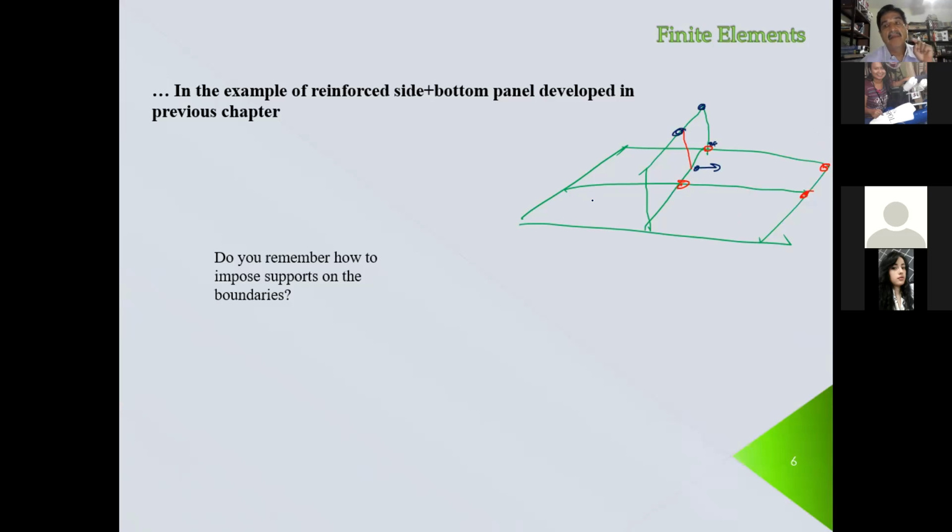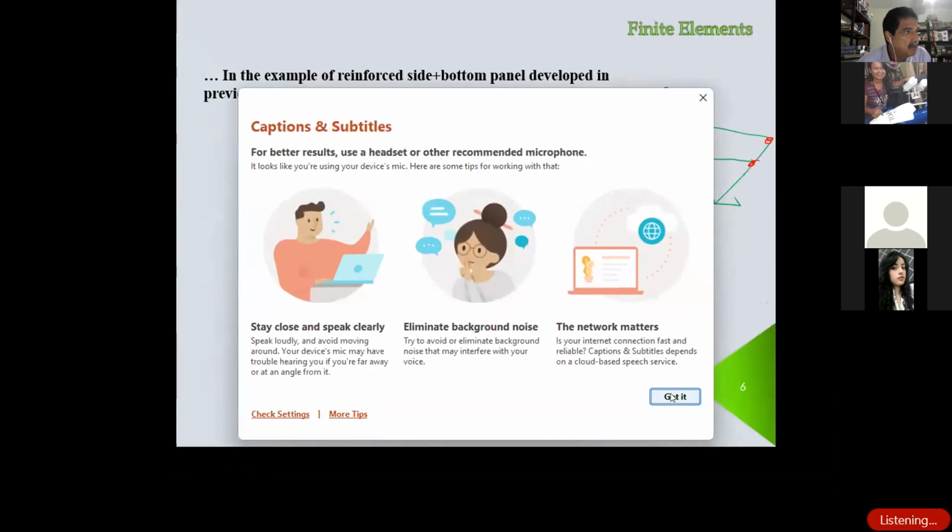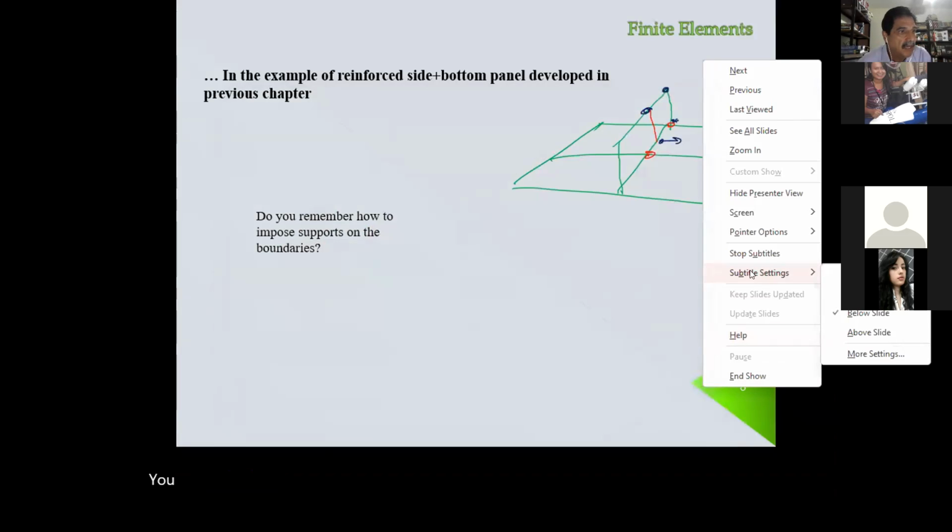And that's something that we mentioned in the previous project. I asked some of the groups to redo this because the connection was not there. In this case, you have to be certain that you connect all elements in your structure. Otherwise, this area here may have very low stress, meaning that it's like having two structures which are not connected. Engineer Isaac will insist on that.